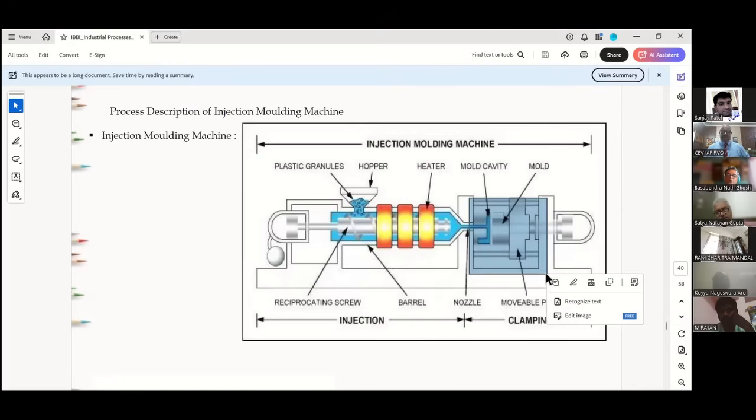The mold has specific types of cavities. These cavities are filled with molten plastic. Once the cavities are completely filled, the mold is removed from the injection molding machine for the cooling process, which may be natural cooling or water cooling. Molten plastics are converted into solid plastics, and when opening the molds, we get the specific shape of the plastic, according to the cavity or required shape.